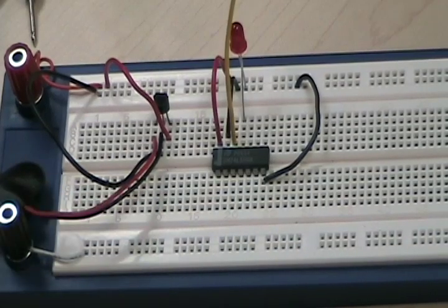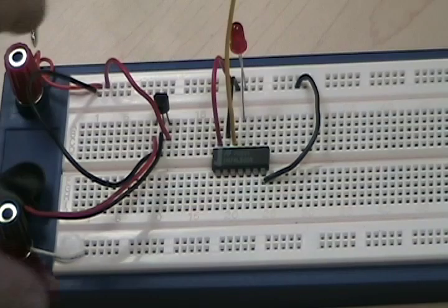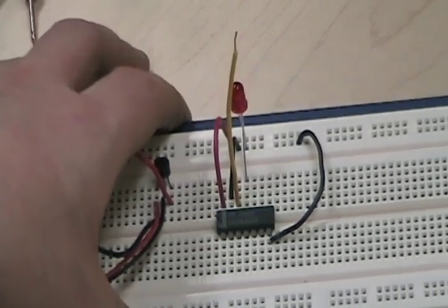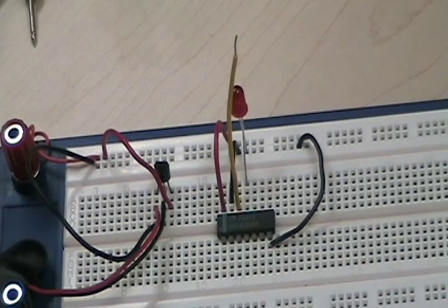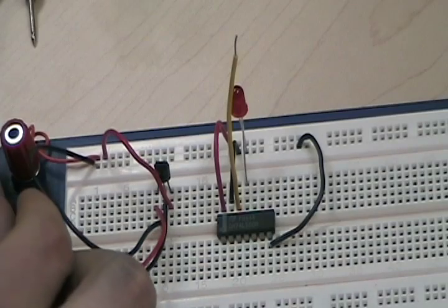So whenever the input selections are correct, our output line will go high. And by high, the indicator LED will light up. So let's experiment with this. Remember how an AND gate works. If both of its inputs are high, then the output will go high. Otherwise, it'll stay low. So let's plug it in.